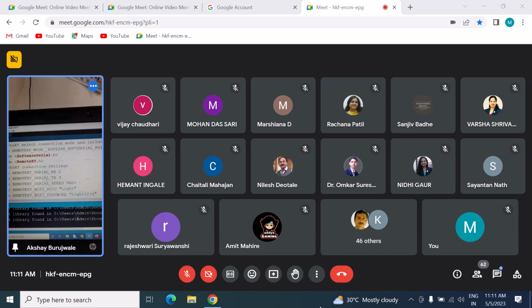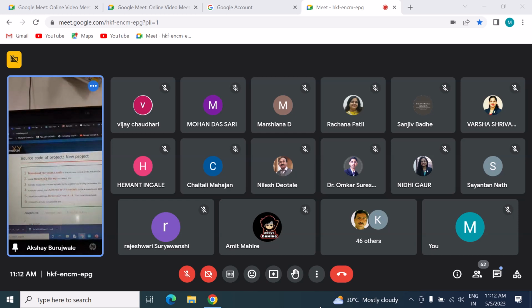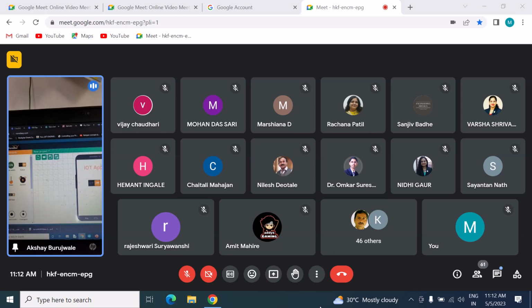We're using this remote XY. See, we are using a Wi-Fi module on pin number 2 and 3, where the RX and TX are connected on our board. And second is the SSID and password. So the SSID is light, and the password is light1234, and the port. These are the common settings we have used. And whatever the API we constructed on this dashboard, we have constructed this kind of scene.